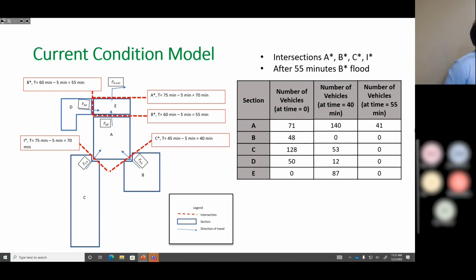I was just wondering about your zero time when you pull the trigger to get an evacuation, and if you considered like an early warning system. We absolutely did. We actually looked into, I forget the specifics, but you can attach it to a bridge parapet wall and it sends a beam down and measures water depth, and you can set it to a certain depth that it will send a signal to somebody to issue a warning. So that's what we looked into, and also the same thing, but you set it on a bank. But really, we were leaning towards the sonar on the bridge parapet wall.